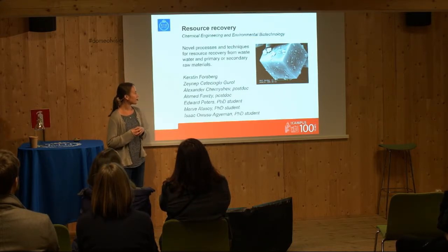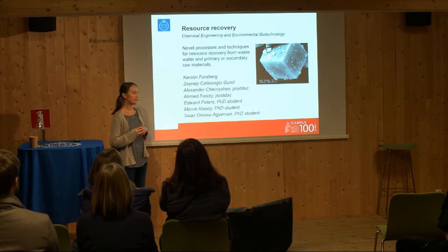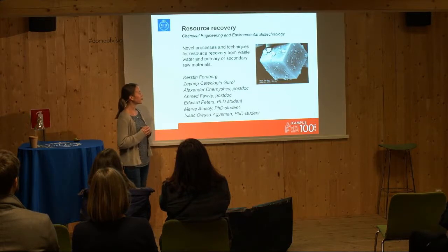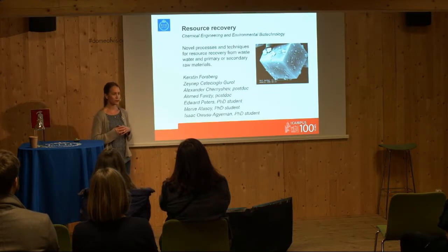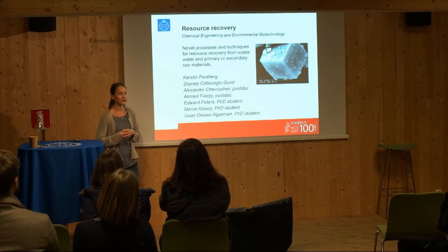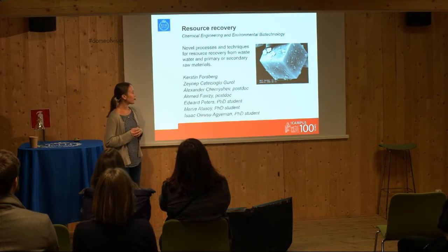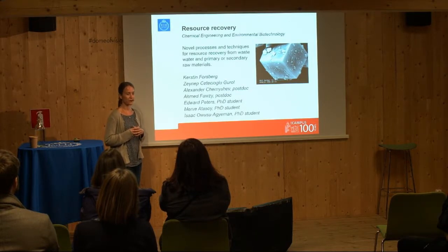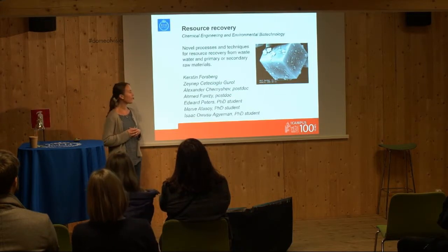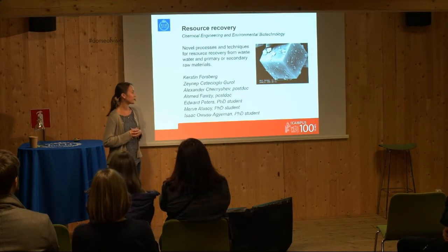But what happens here is that over time the mixed acid will contain more and more of these metal ions, and you can only use this acid mixture up to a certain point. When the metal ion concentration is too high, you have to start over with new fresh acid because it loses its ability to pickle. And then you end up with this waste mixed acid with a lot of metal ions in it. And what was done at that point was that it was neutralized, and then it was put on a deposit. But we worked to develop a process how to recover the acid and also the metal value.